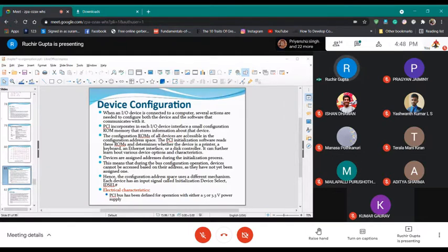And of course, you can also understand that you can connect only 21 devices, because the lower address lines will be used for transferring the data in configuration memory, and the kind of operation is also specified using that. So out of 32, 11 will be used for configuration data transfer, and these 21 will be used for identifying the device. Does it make sense?